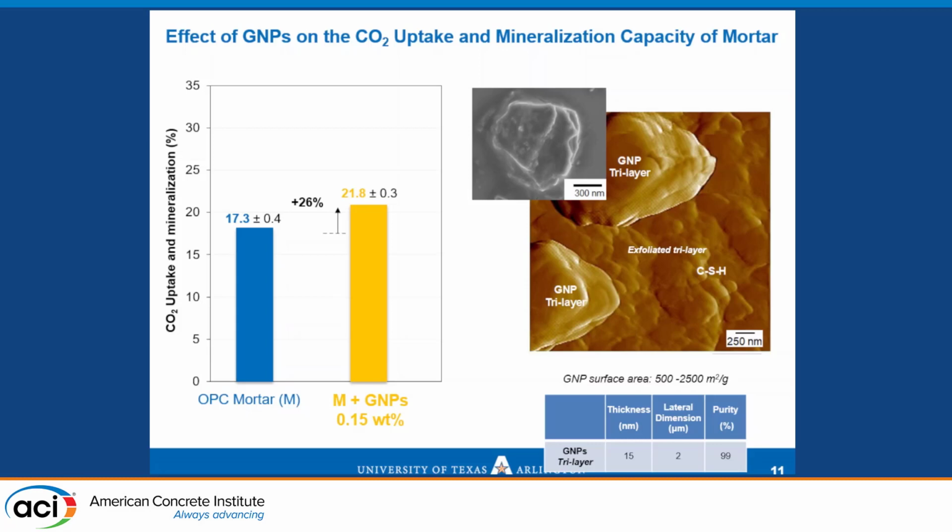Now, the whole project that we submitted to NSF, the idea was that maybe we can combine the two ideas: that we can make good use of porous surfaces, including porous channels in concrete, to increase the CO2 sequestration, in a similar way to how we can use recycled aggregates inside concrete. That would also give us some porous pathways, and at the same time find a way of accelerating and enhancing the hydration kinetics, but this is a job for the nanomaterials. Nobody else can do it.